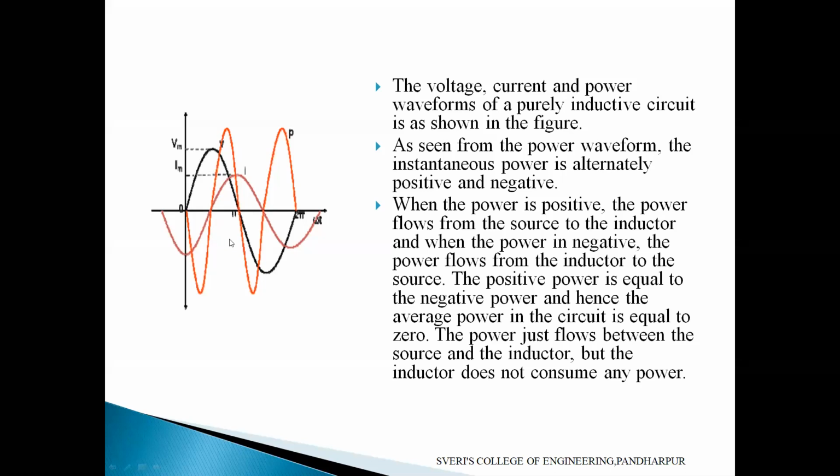In one cycle of 360 degrees, it will complete 2 cycles of the power. Here you consider minus maximum power, and here plus maximum power. Both positive and negative power supplies are there, for the power consumed by the inductor. At the average value, the positive cycle cancels the negative cycle. So the average power for the AC circuit with a pure inductance is 0.